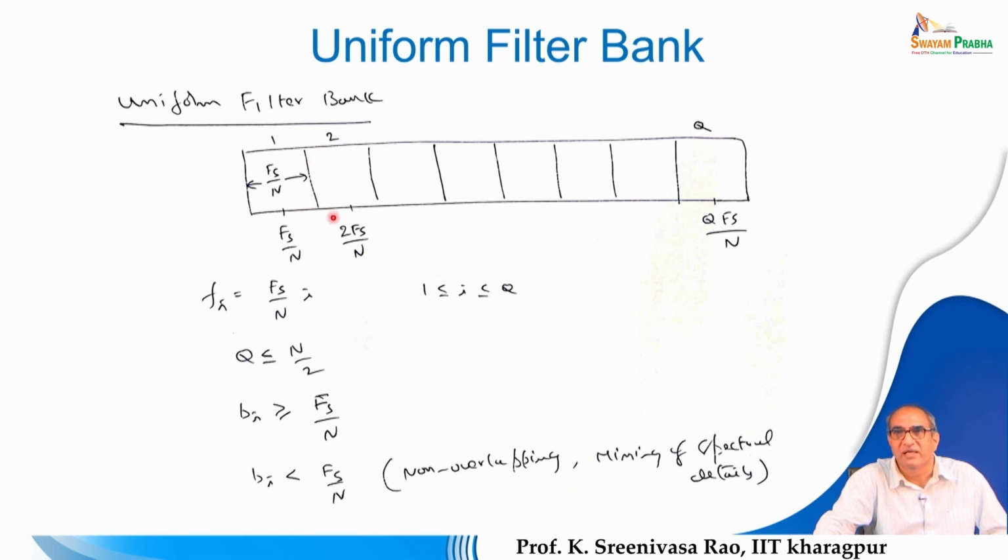If the filters are overlapped, the entire frequency range is taken care of by all the filters together. If they are not overlapped, we leave out some frequency content between successive filters, which is not analyzed, and by missing it we may lose some information later for the purpose of speech recognition.